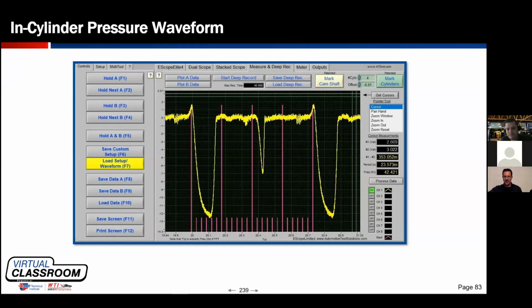Cranking vacuum. But here, what do we see here? We don't see 1 or 2. We see about 7 inches of vacuum. Excuse me, 7 psi negative, which is about 14 inches of vacuum. And then suddenly it disappears. I don't know what's going on yet. But then I come over here, and this is the rest of my intake stroke from here to here. And I've got pocket differential between here and here of about not 2 or 3 psi differential. We've got like 12 or 13 psi differential. And you could clearly see leaning towers here. So this is substantial.